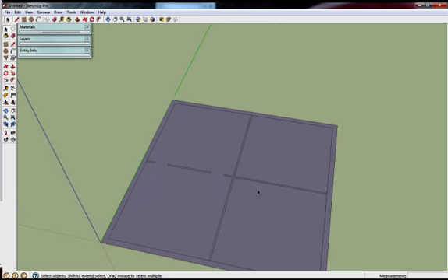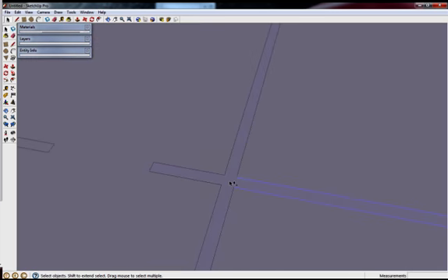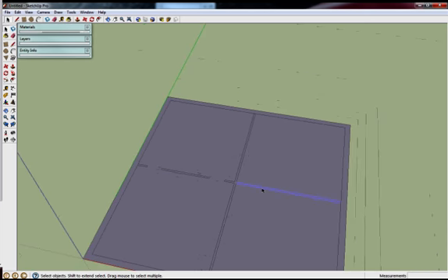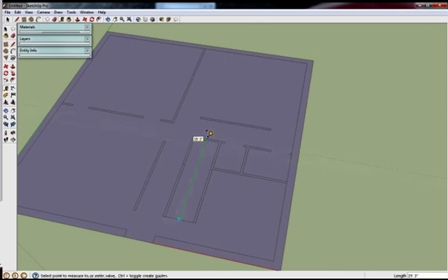Say we need to move a wall. Use our selection tool, the space key, draw a box around the wall to be moved like I am doing, or select the 2 lines individually. As you can see, it may be better to select the 2 lines as I am having to unselect what I don't want to move. Using your Move tool, move the wall to the desired direction and distance, here 2 feet. Whatever is attached to the lines will move, so you don't have to worry about redrawing the lines on the other walls. As you can see, I have finished drawing the first floor and am about to draw the stairs.